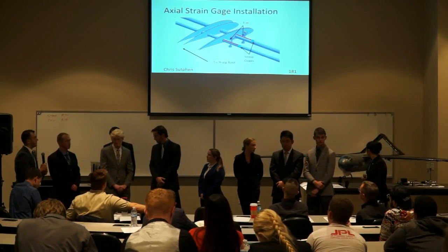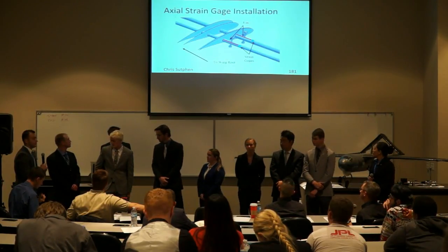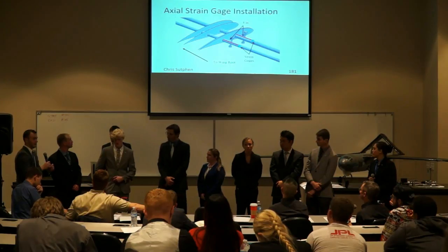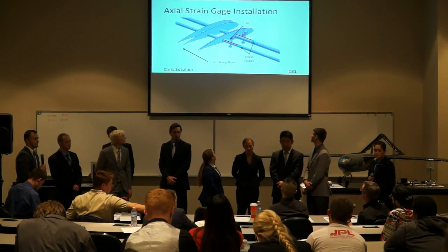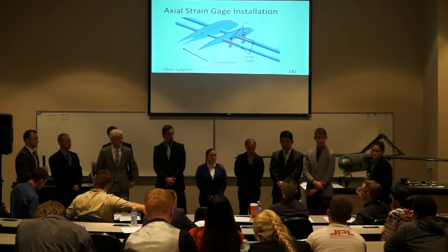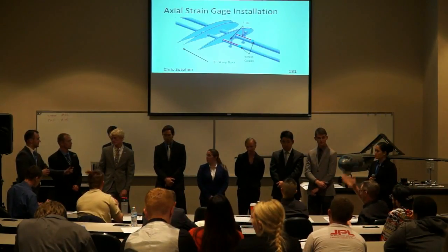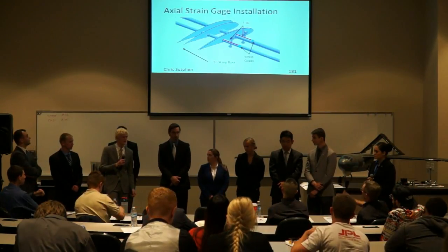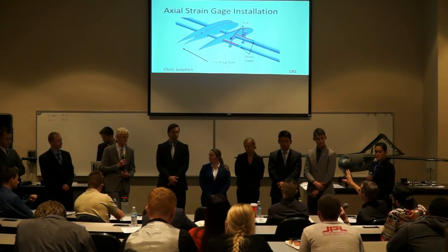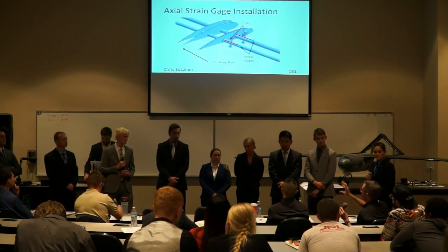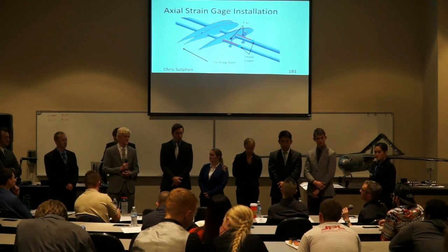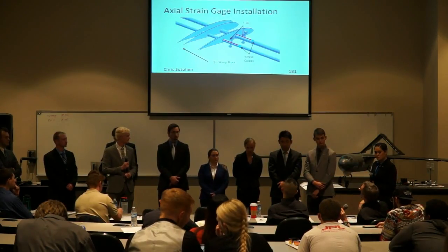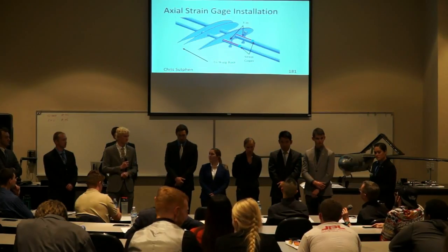So that's basically the pin that connects the outer spar to the inner ferrule. You got a lot going on there, and that's likely to affect the strain gauge. You got a hole, and then of course no load is transferred from the hole. You got where the tube chops off, no load transfers through that, so that leaves some load. You've got the ferrule underneath there, and that perhaps stiffens the whole thing up. There may have been better places to place the strain gauges.